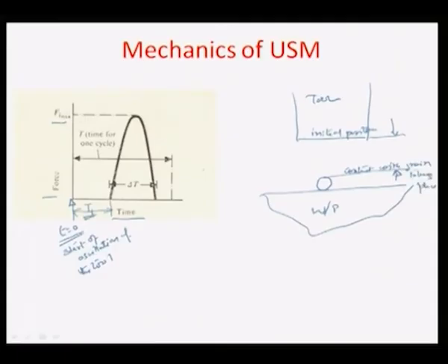Okay. Now, the tool has come and it has started to do the ploughing action. The tool is now somewhere here and it has just about started the ploughing action, and therefore, there is always a reverse reaction force available from the grain onto the tool, which is being plotted as a force in the force time diagram here. Really there is no deformation until a critical value of stress is reached at this level here, where it can start to penetrate inside the workpiece at this particular interface.